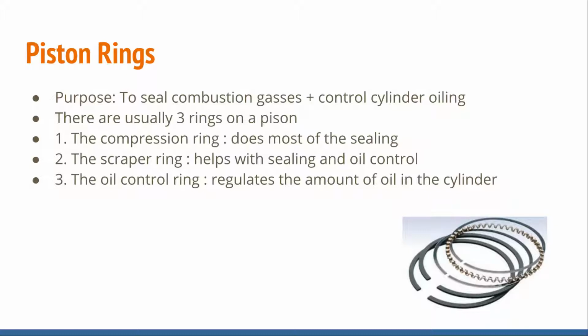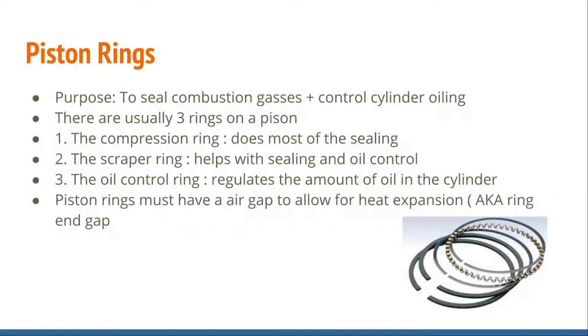If you're consuming oil and if you're blowing blue smoke, we're going to talk about all that later. So anyway, piston rings are very important. It takes the oil away from the cylinder, puts it back down in the crankcase. Piston rings must have an air gap to allow for heat expansion, also known as ring end gap. So when your piston ring is installed on the piston and the piston is installed in the cylinder, you're going to see that gap is going to be far smaller, but you're never ever going to have the piston ring end gaps touch.